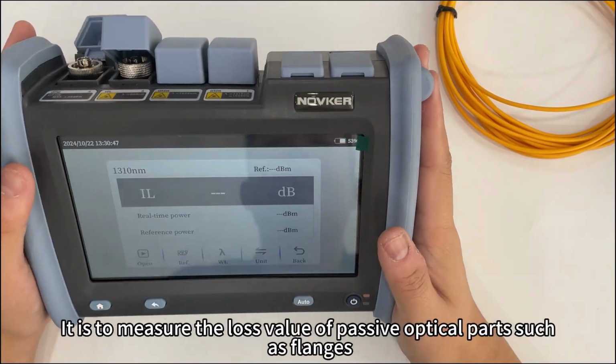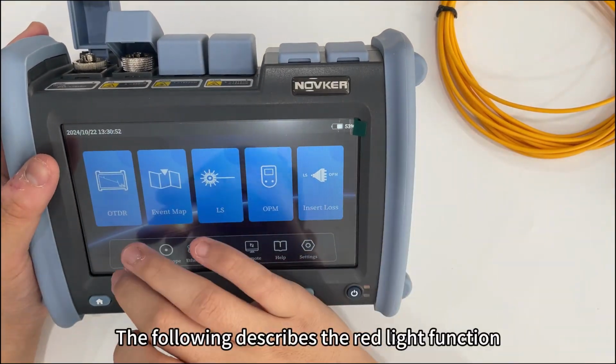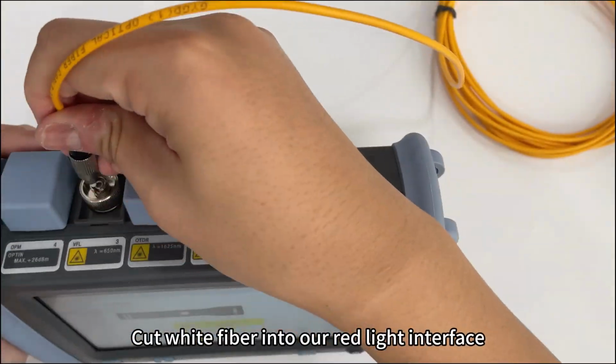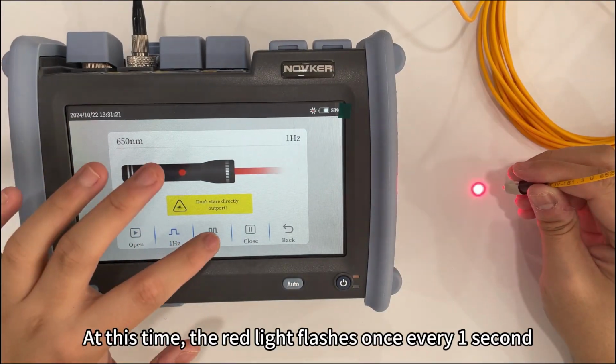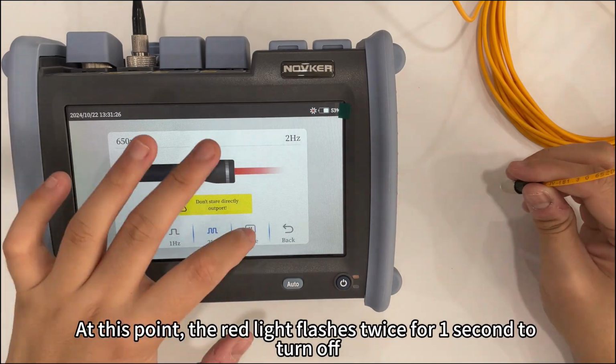Optical loss test function. It is to measure the loss value of passive optical parts such as flanges. The following describes the red light function. Plug the fiber into our red light interface. After opening it, you can see normal red light emission. Switching frequency, at this time the red light flashes once every 1 second. Switch to 2 Hz, at this point the red light flashes twice per second.